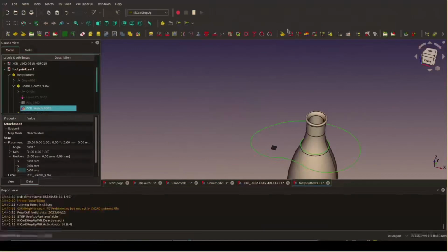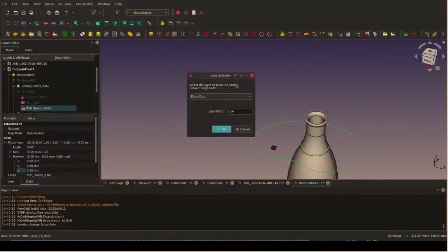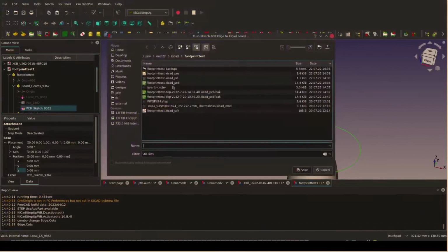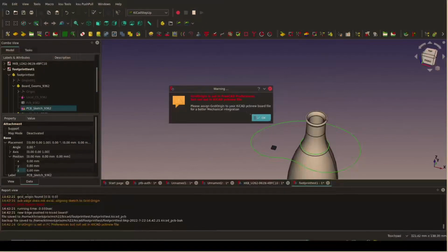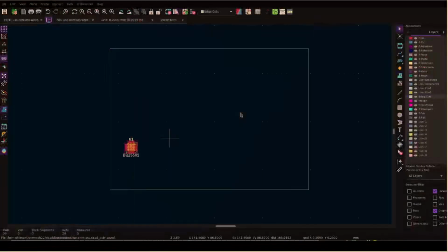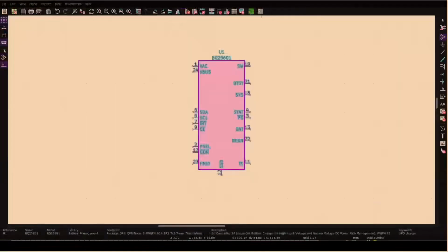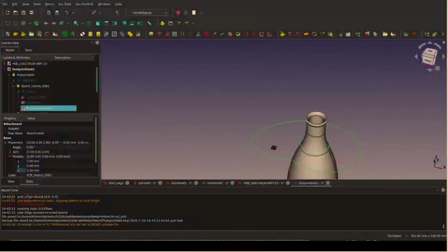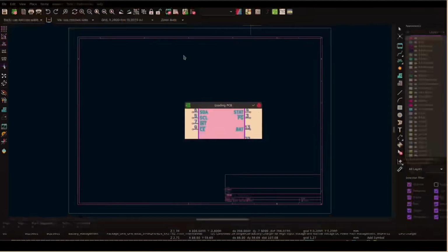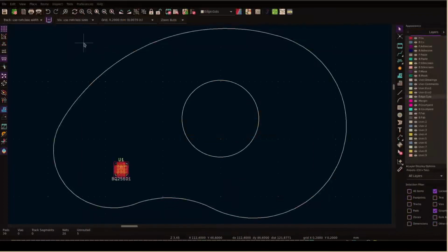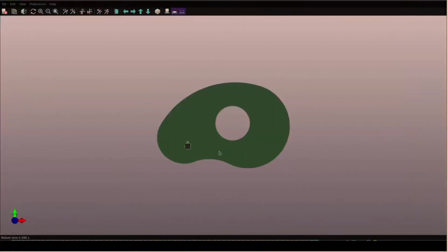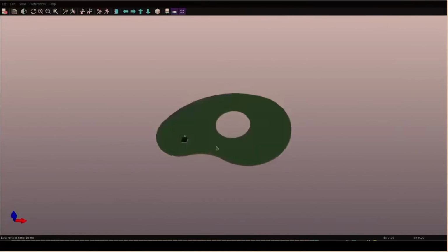So then we can now take this and then push that sketch to a PCB. And this will actually overwrite our KiCad file with the new shape. So then over here, we need to actually close this file and open it again, because it's now being edited outside of KiCad. And now we can remove the old outline, and we have this one. So yeah, that's how that works. And I'll show you another thing.